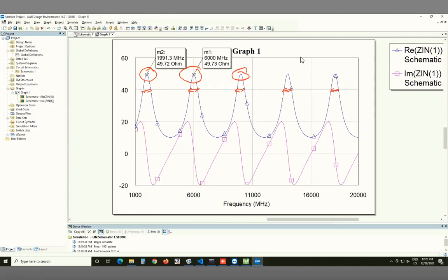So the reason I was trying to emphasize this point is that we talked about this idea of fractional bandwidths, right? The absolute bandwidth, if I define those arrows as whatever I've drawn there, looks the same, but the fractional bandwidth is actually getting smaller, because what is a fractional bandwidth? It's with respect to the frequency.